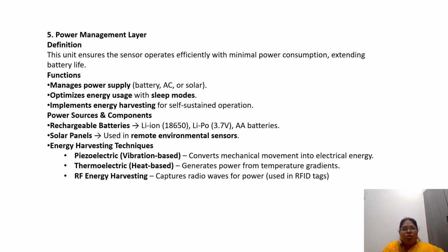For the power sources and components, we can use rechargeable batteries, that is lithium ion batteries and lithium polymer (LiPo) batteries. We can also use solar panels, which are more advisable in remote environments and remote areas. We can straightaway use the solar panel. And next comes the energy harvesting techniques. We can use piezoelectric, thermoelectric and RF energy harvesting.